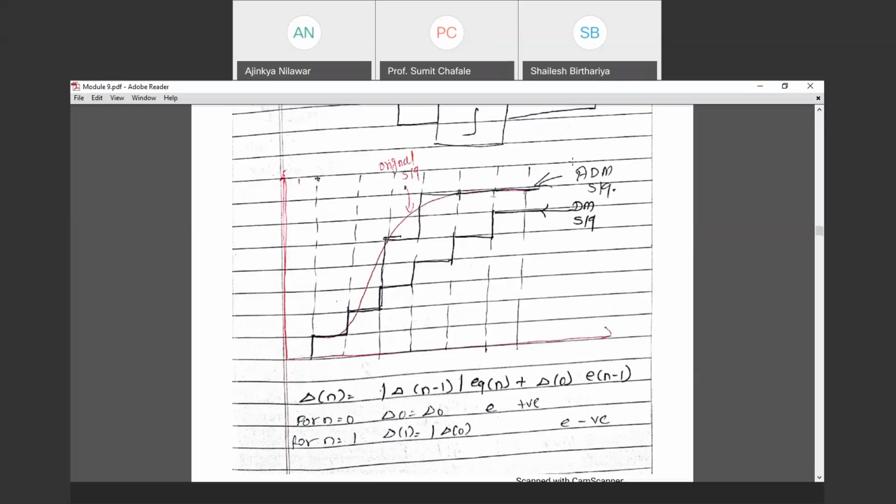In the case of delta modulation, we are having 1 bit per sample, but we are using the uniform quantization level. That means there is a huge quantization error if we are using the delta modulation scheme. For reducing that quantization error, we are using adaptive delta modulation, which will result in 1 bit per sample with exact value. That means reducing quantization error and sending appropriate information. So this is how we are generating signals with the help of adaptive delta modulation.